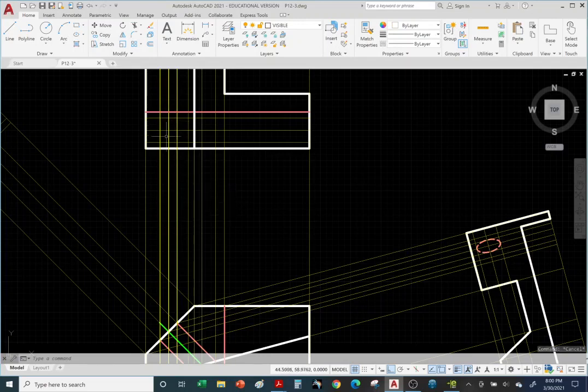So the hole is in here. We know the center line, right? There's the green center line as it exits the solid at the white visible object line. So we know this line is for the center mark. Here's the center, here's the left quadrant, right quadrant, and we already have the construction lines for the top and lower quadrant of this hole.